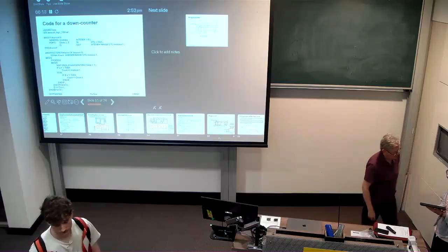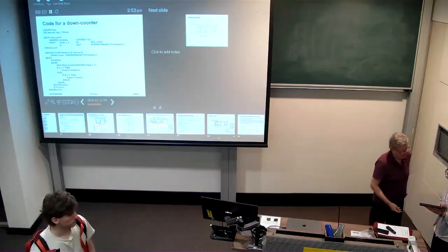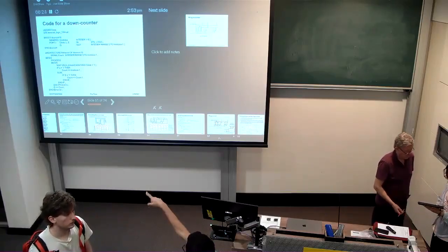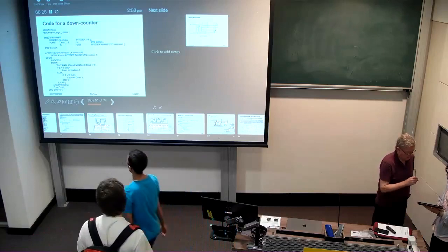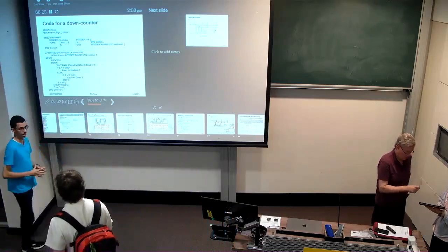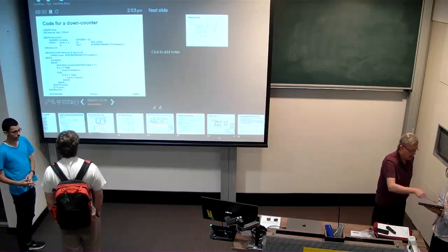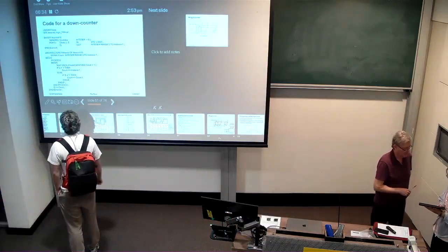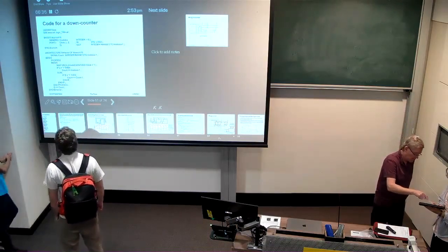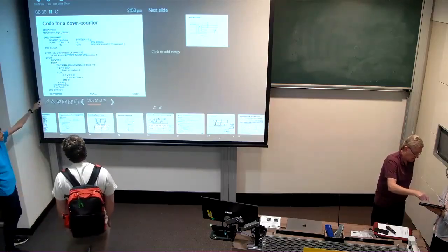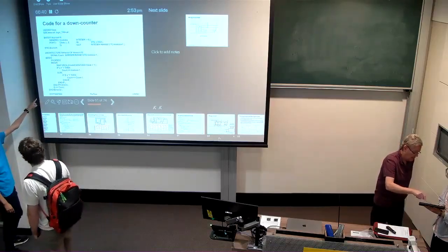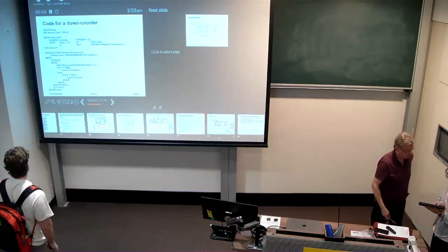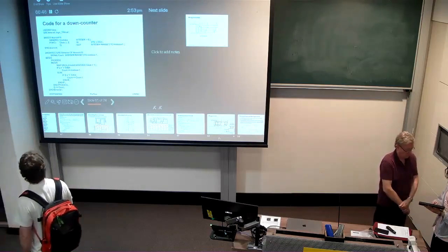The generate stuff is not usually complicated to write. It's the behavioral process stuff that's complicated, where something looks at this and you definitely don't want D to change until P2 is 0, because if it changes before that, it's possible. Writing this code, the synthesis will read it and know what to do with it, but it'd be so much slower.